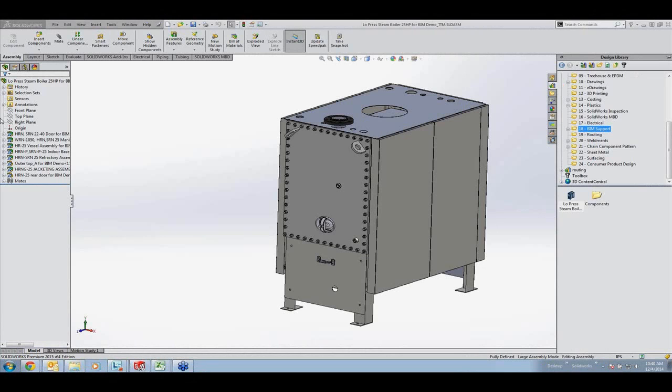Of course, I messed up there. Trying to make them orthogonal so that it'll create the 90-degree elbow there. All right, very easy to fix if you do make a mistake. I'm just going to go ahead and attach it there. Preview is a little iffy sometimes, but once I hit accept the sketch, you'll see that it did work properly.